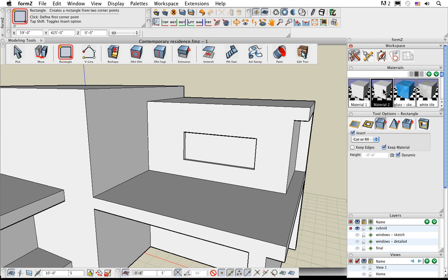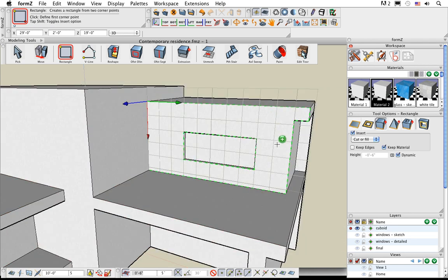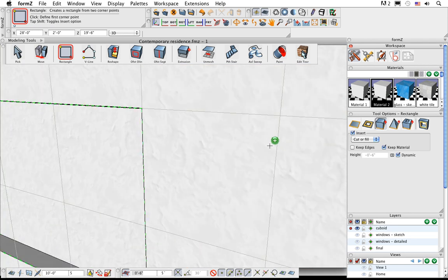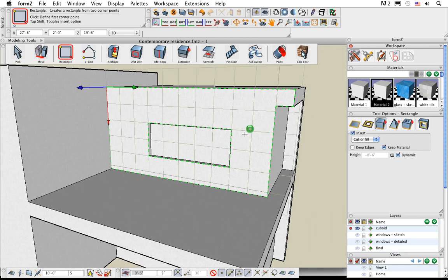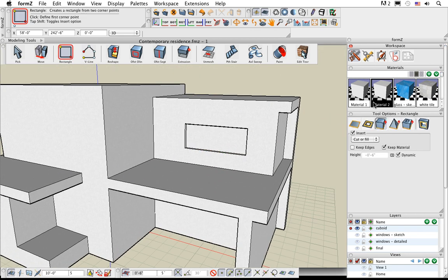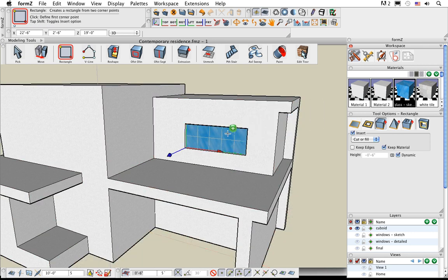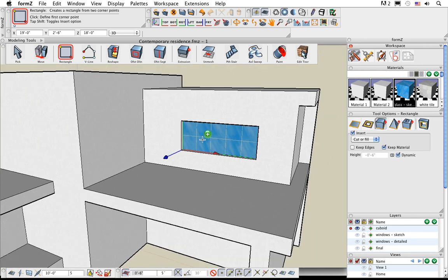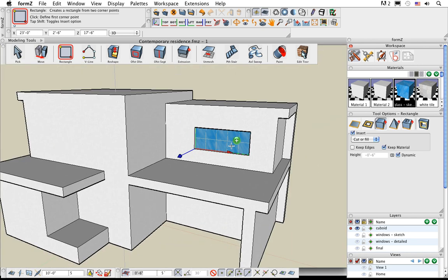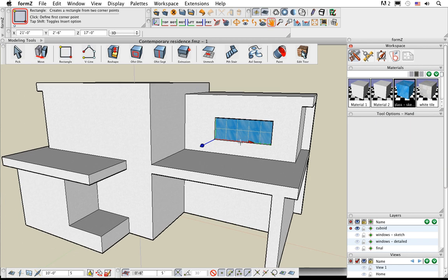Now I can take my material and simply drag and drop it onto the object, and now that stucco pattern is applied to that entire object. Now for the windows, I don't want stucco. I want it to be a transparent glass. So I created another material, and I drag and drop it, and I'm going to hold down the Command key on Mac or the Control key on Windows to apply it to just one face of that solid massing model that we have. So there we have a nice window that's a sketching type window just to visualize where these windows are going to be placed.